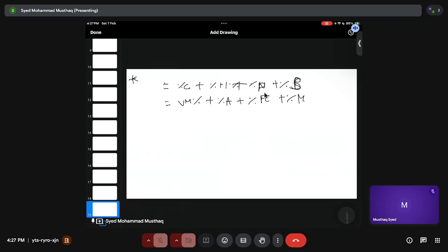Let's move on to the next point. Now, how do you define this? You have inherent moisture, the moisture that is normally trapped whenever you have some hygroscopic compounds, so they trap moisture. That is common. Now, how do you know the amount of moisture that is there? You do heating up to 110, 115 degrees centigrade for 1 hour.